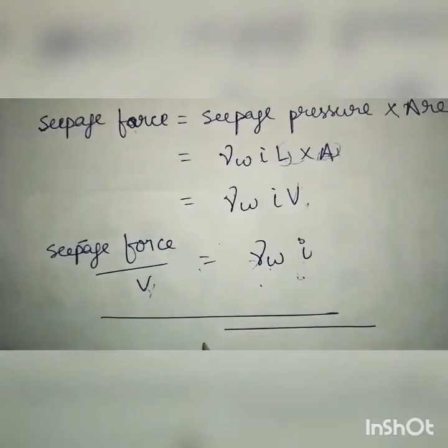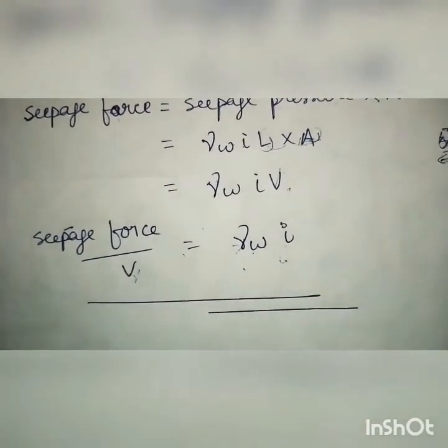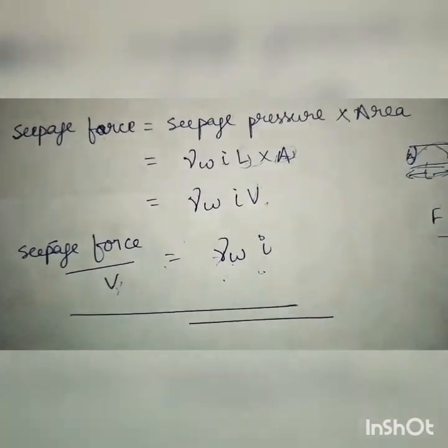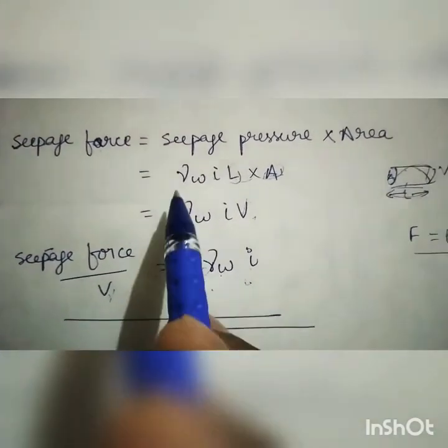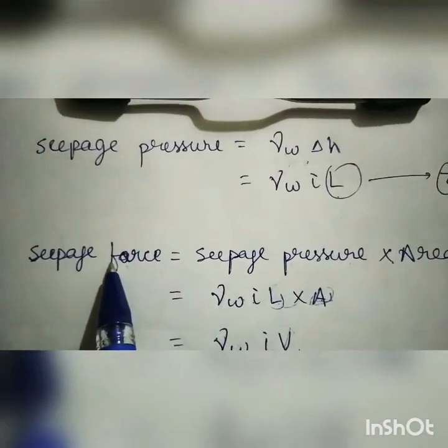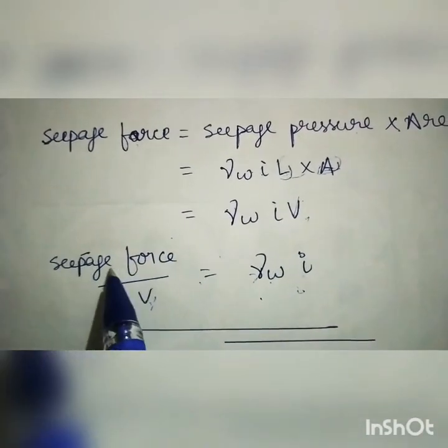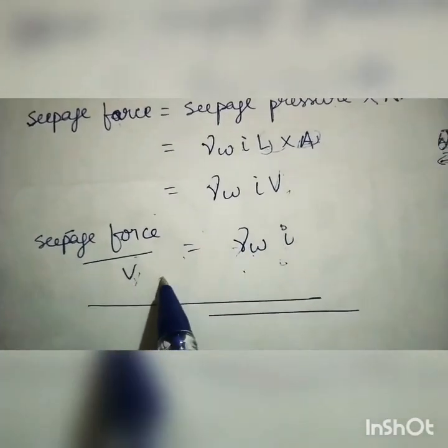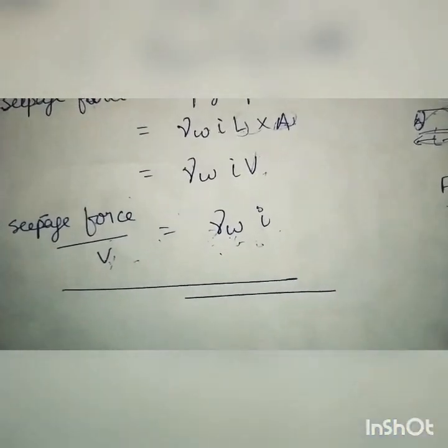So till now we have covered seepage, what is seepage, under it we have also seen permeability, and then seepage pressure, and after that seepage force, and we have also derived seepage force per unit volume, which is gamma W into i.